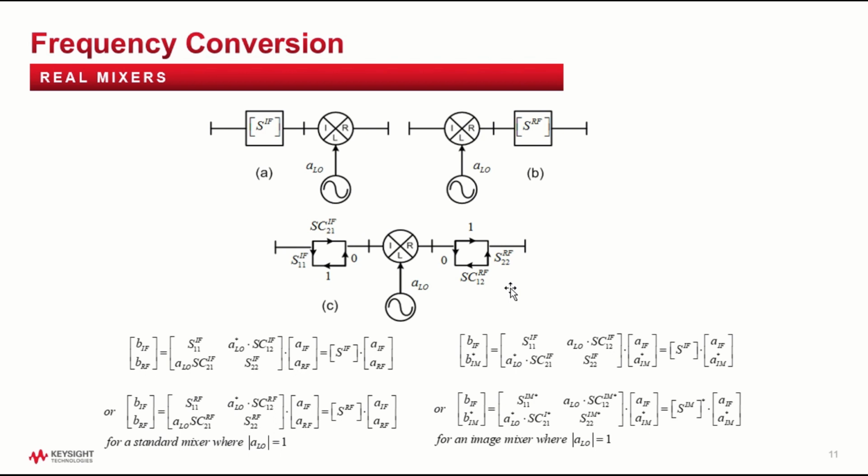Now we have to accommodate this in our error correction. If you look at the error correction terms in the VNA, when we do a full mixer match corrected error terms, the error terms have to be internally conjugated to get the right error correction.